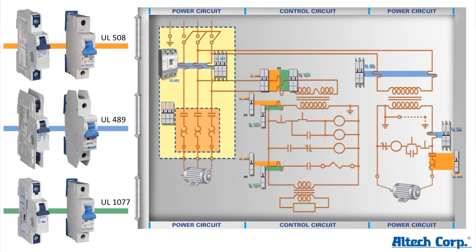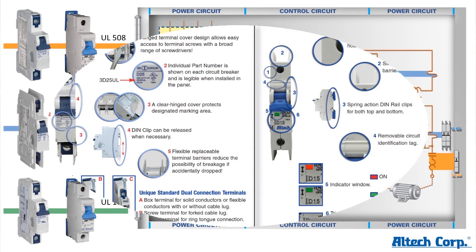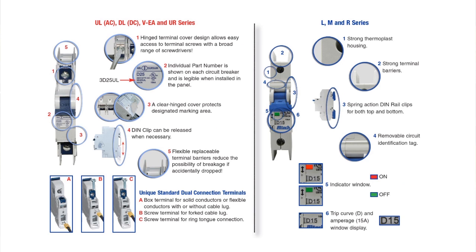In addition, you have a 508 breaker, which, by the way, we were the first in the industry promoting, a UL 508 circuit breaker. I call it a circuit breaker because it looks like a circuit breaker, but according to UL it is just a manual motor controller, but with disconnecting means. Customers used to use these miniature circuit breakers, which also came from Europe, as switching devices. They were initially only certified to, or recognized under, UL 1077.